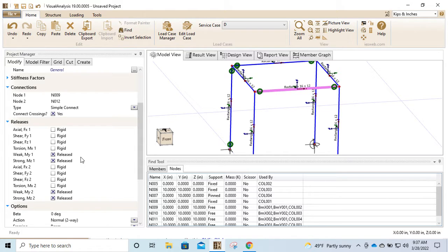Well, that would be like a global stability thing you'd have to take into account, right? Because if you fix this node, and this was just a cantilevered column, it just stood up here, we erase everything here, right? If this was a fixed node but it was released, this column could just rotate around in the two directions, because it can't provide any force there, right? We're saying that it's released. There's no difference between the member and the member, right?